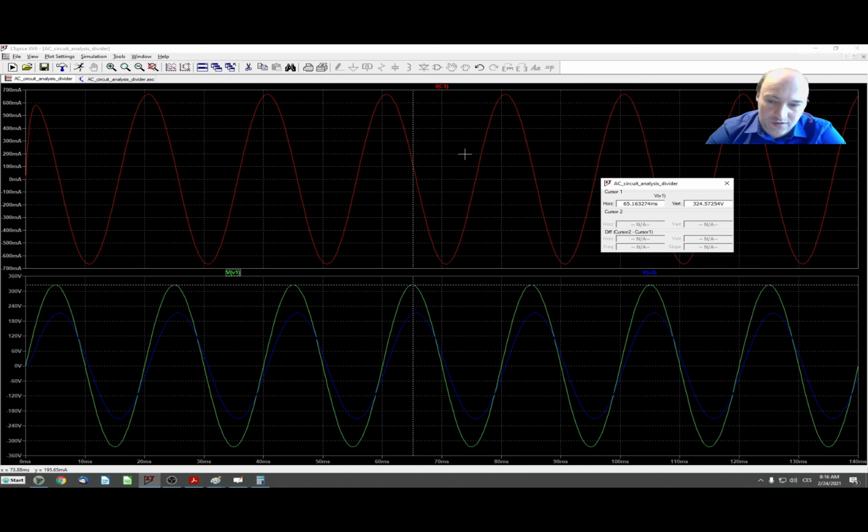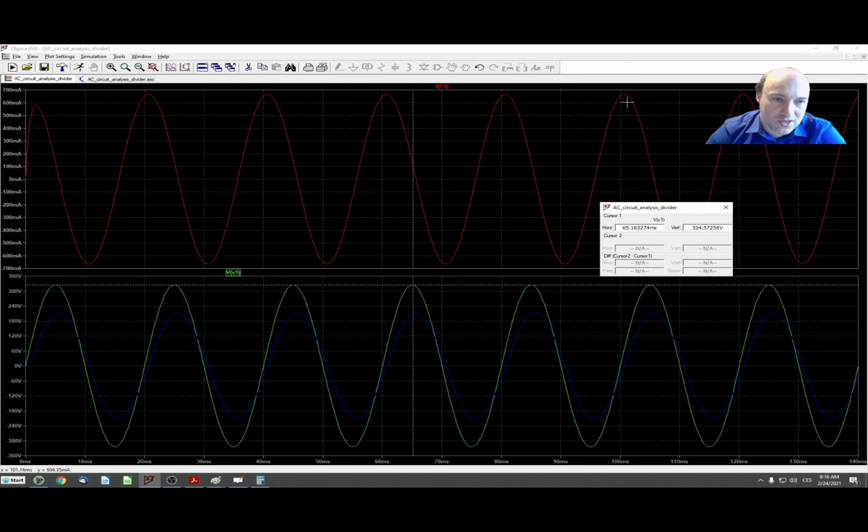And from the lectures you know that our method of calculation is working in steady state. So it will give us correctly the calculation of voltages and currents here in steady state, but if we would like to calculate those peaks in the transient, we would need to use a set of differential equations.